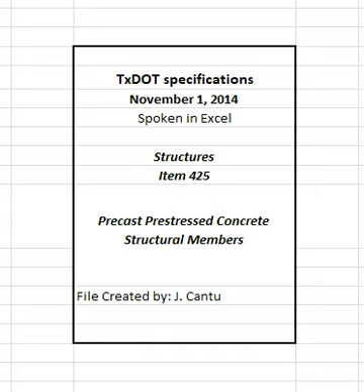Package prestressing steel in containers or shipping forms for protection from physical damage and corrosion during shipping and storage. A corrosion inhibitor must be placed in the package or form, incorporated in a corrosion inhibitor carrier type packaging material, or applied directly to the steel when permitted. The corrosion inhibitor must not have deleterious effect on the steel, concrete, or bond strength of steel to concrete. Inhibitor carrier type packaging material must conform to the provisions of Federal Specification MIL-PRF-3420G.